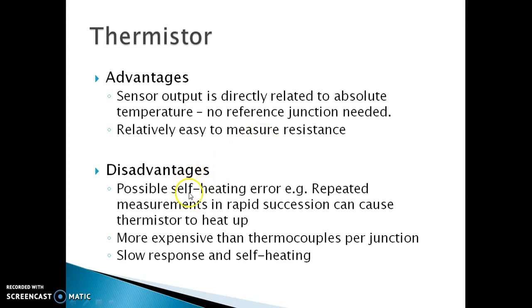The disadvantage being, in thermistor we have the self-heating problem, wherein since it's the change of resistance, it is again related to the power, and if power increases, we get heat dissipation which is generated, and which is the self-heating power.